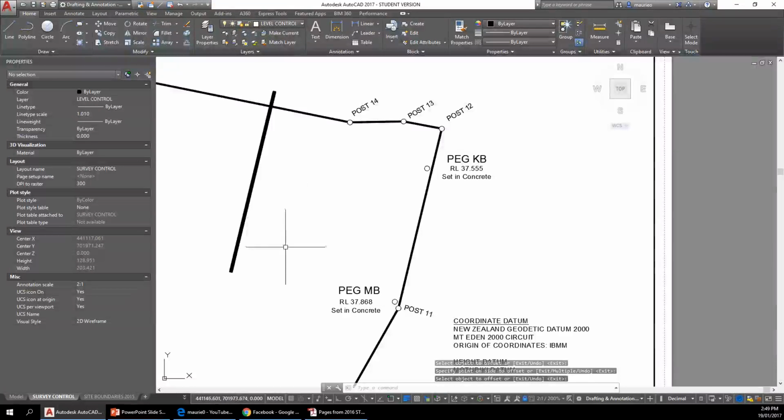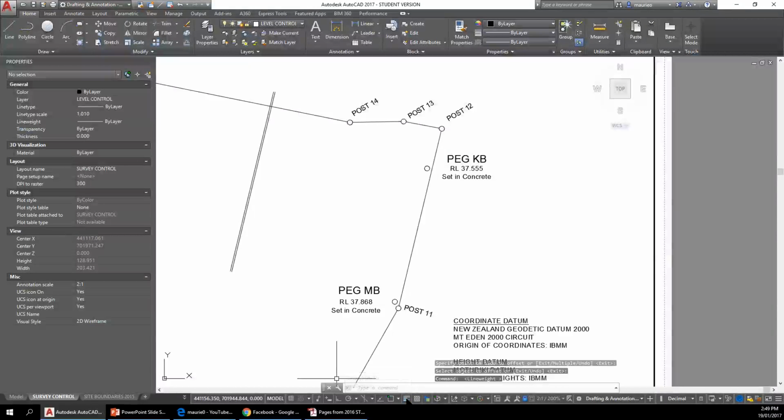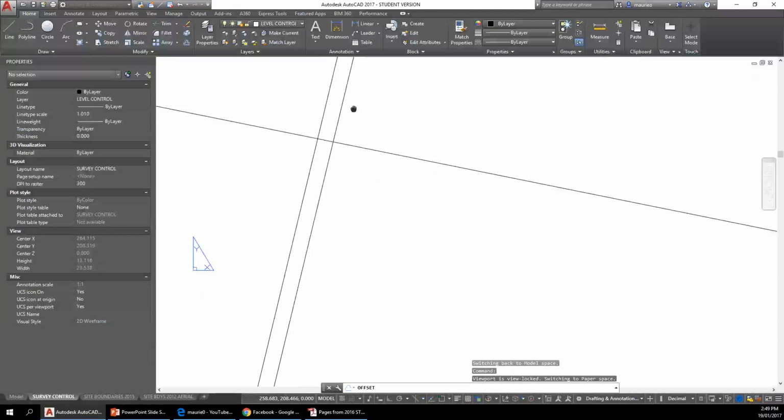So there's a number of things we can do. One is, you'll see down here, this is the line thickness or the line weight that's on. I can turn that off, and you can see our two little lines there now, which might be a little bit easier. And now I'm going to offset this one here 5 meters. So O for offset, and then we're just going to go 5, enter, and select the offset. And so now we can zoom right in there, and we can see that there are 2 points where we want to show our valves.